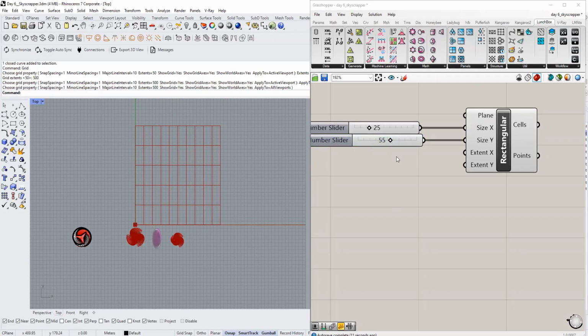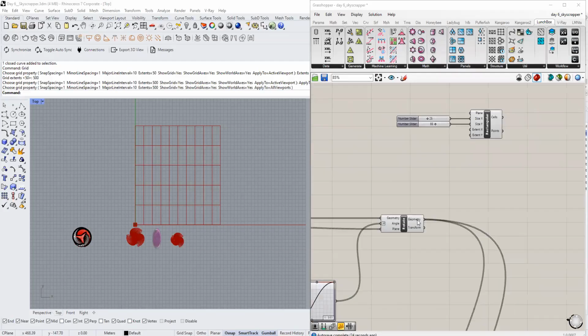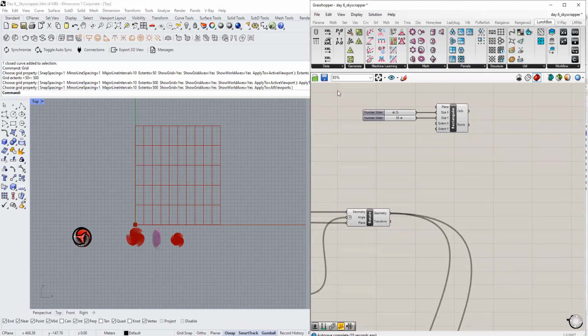So the first thing to ensure in the grid is cell size are big enough. Second thing to ensure is the number of cells. The number of cells should be equivalent to the number of flow plates we are placing. So if I have 67 flow plates, I need to make sure I exactly have 67 cells for placing the flow plates. If I have more or less, there's going to be a mismatch in data, which we do not want to have.